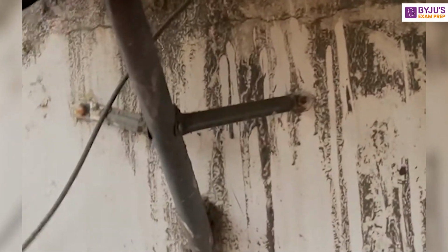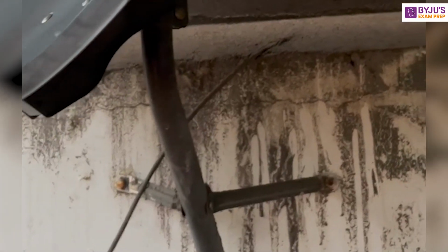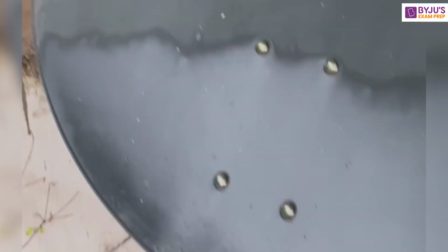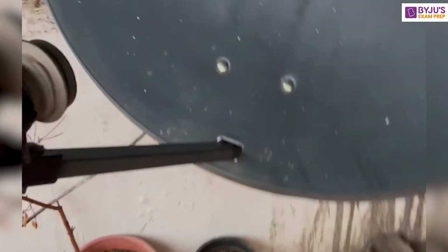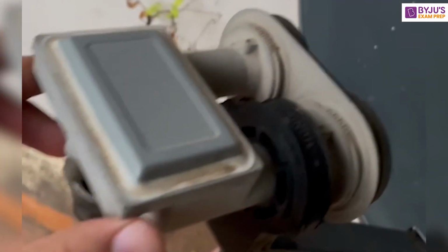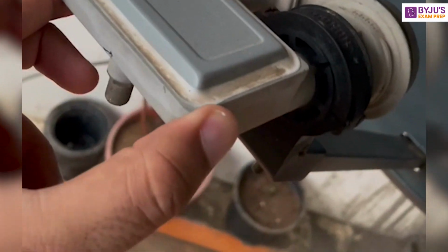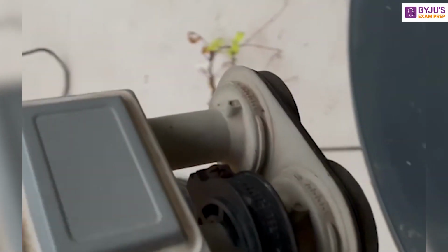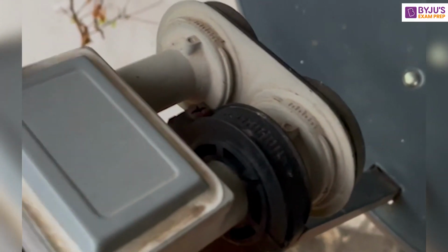So this is basically the support structure of this reflector, where this long pole is commonly known as the mast. This is the parabolic reflector, yes, the dish reflector, as you are able to see. This is basically the arm supporting the LNBF, the LNBF arm. This is the LNBF holder, and here we have the LNBF, the low noise block down converter with the feed horn. Yes, I'm also going to talk about the internals of it. How does it actually gather the electromagnetic energy?